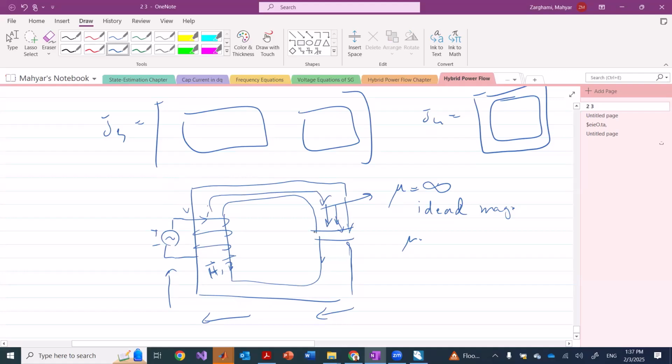When it reaches the air gap, it not only basically goes through this path, but also a little bit around that direct path. This is called the fringing effect, which practically, as you can see, it's as if the cross-sectional area has been increased a little bit by 5%, which impact is to reduce the reluctance, not to increase the reluctance, because reluctance is L over mu times mu 0 times A for the air gap. When A increases, it's as if the reluctance decreases. Okay, so this is the difference between the fringing